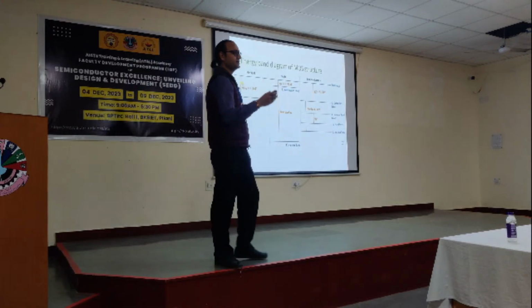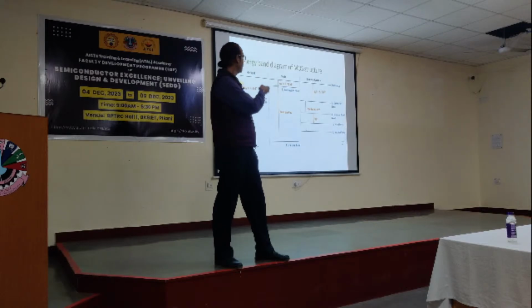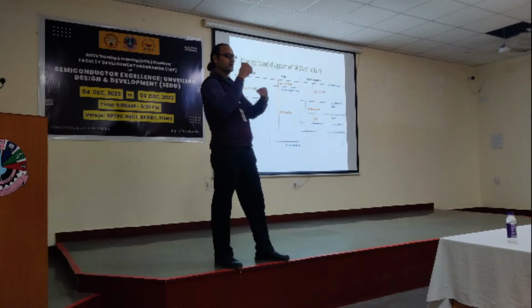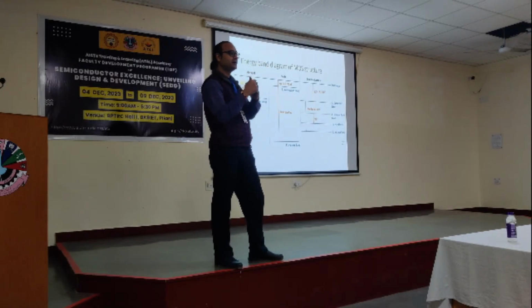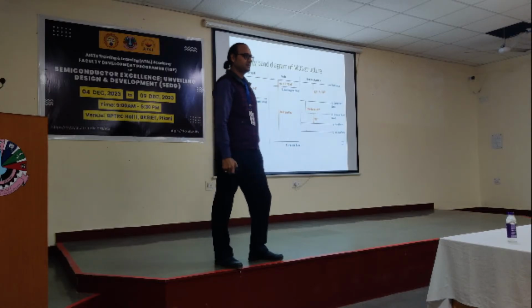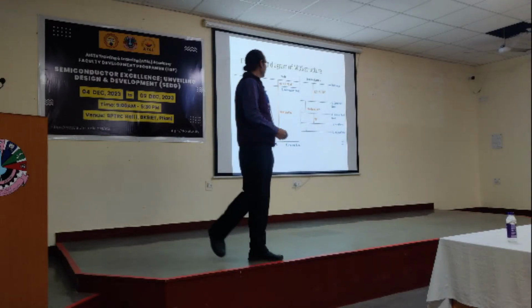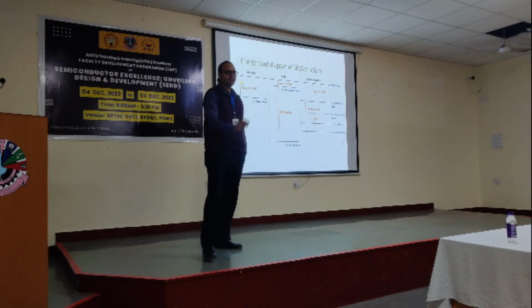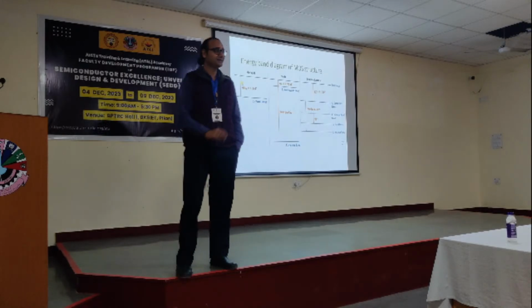The oxide capacitance is epsilon, the dielectric permittivity of oxide, divided by the distance. So from the observations or requirement, we will first calculate what the capacitance per unit area COX is required. We know the dielectric permittivity of oxide. Determine d from there. Is that clear? The discussion should be such that there is no confusion.